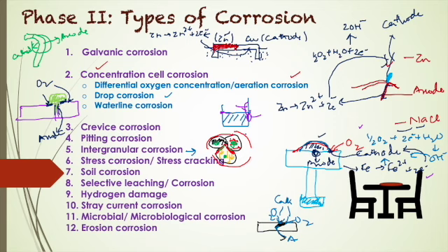Other corrosion factors in this case are the differences in pH. There can be a presence of unburned carbon in the cinders, or else the soil of one city or one area can be less aerated as compared to the other one. So in that case, aeration concentration cells develop on that particular pipeline. So this leads to soil corrosion.